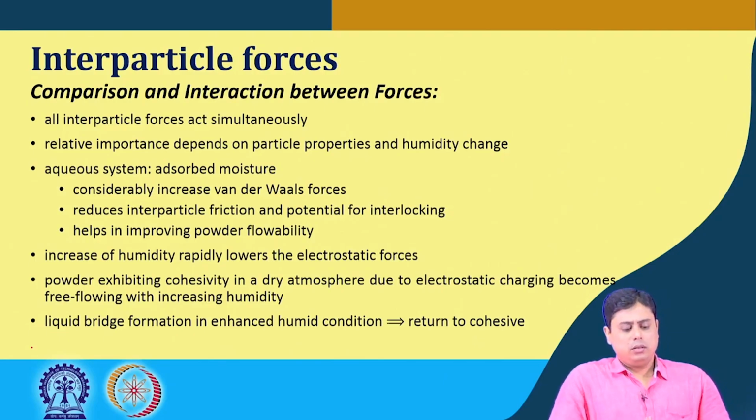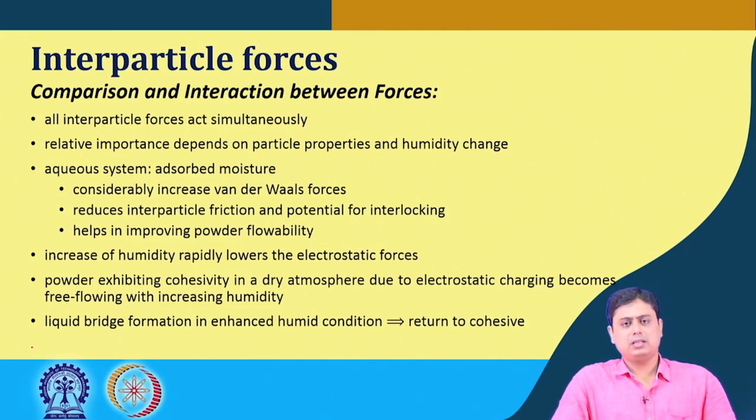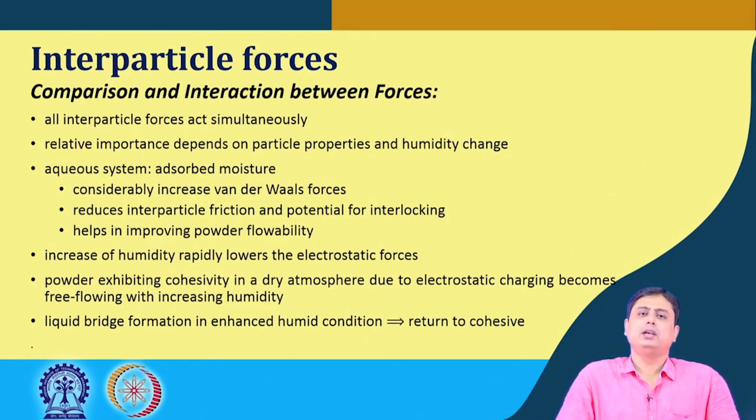So, increasing humidity rapidly lowers the electrostatic forces, and the powders that are cohesive in nature in dry atmosphere, due to this electrostatic charging between them, become free flowing with increasing humidity. But again, it can come back to its cohesive state if the humidity is sufficiently enhanced to a greater extent. The research has shown this kind of properties as well.